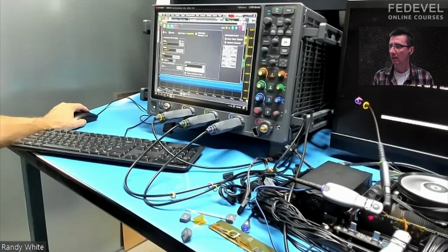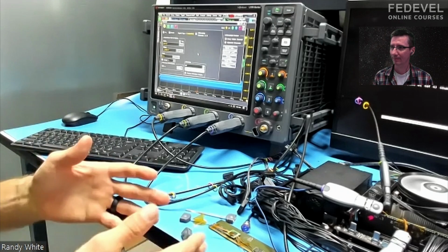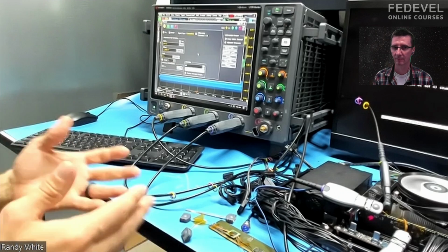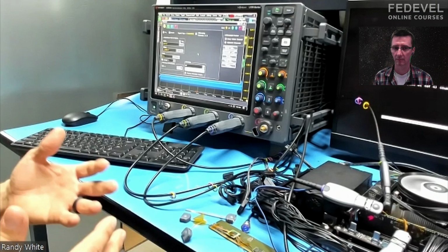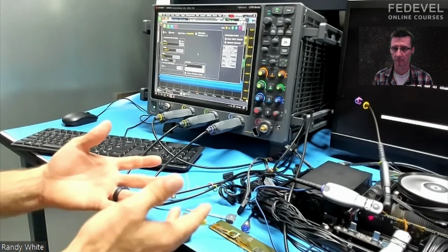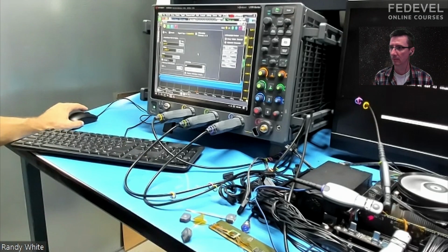That is an excellent memory. Yeah, we talked about this before. That process that you describe of removing the effects of the interposer, because yeah, you will see reflections and non-ideal signaling from just having that connection there, we call that process de-embedding. Okay, de-embedding.